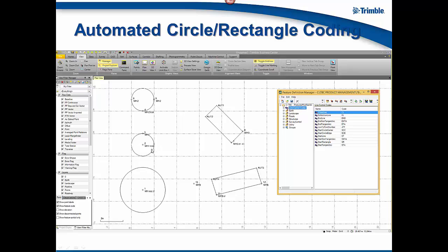In case you don't know the radius and you want to position the second point on the rim, you can just code SCC as a start center circle and define with the second point where the rim is. Or if you cannot access the center of circle, you can collect 3 points on the rim of the circle.